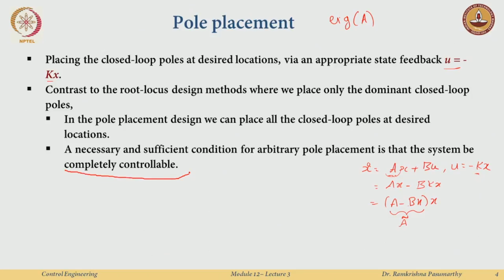So if I just write down some equation, right? So just say I have x1 dot is, say, x plus some k times u. Okay. So what is the eigenvalue of the uncontrolled system? The eigenvalue of the uncontrolled system is at plus 1. Okay. Now, if I say, can I place this at, say, some value minus 2?